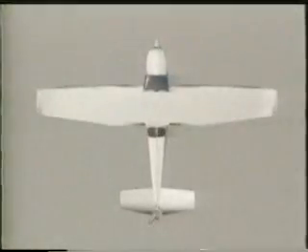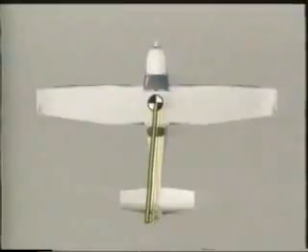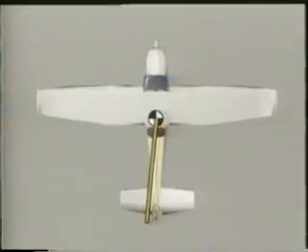One of the key aerodynamic elements of a spin is the effect of aircraft loading on recovery. Since the airplane spins about its vertical axis, a forward CG provides a responsive rudder, since the rudder moment is long. However, as the center of gravity moves aft, the moment decreases, and rudder effectiveness is reduced. In extreme cases, the rudder may be ineffective in arresting the yawing motion incurred in a spin, making it impossible to recover.